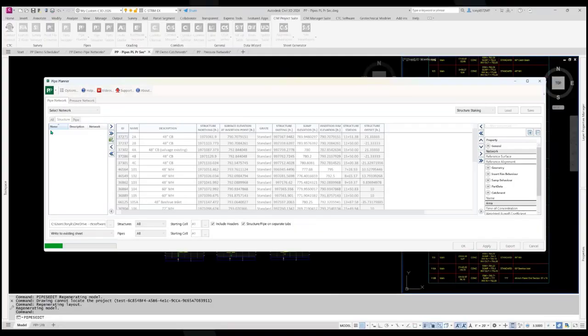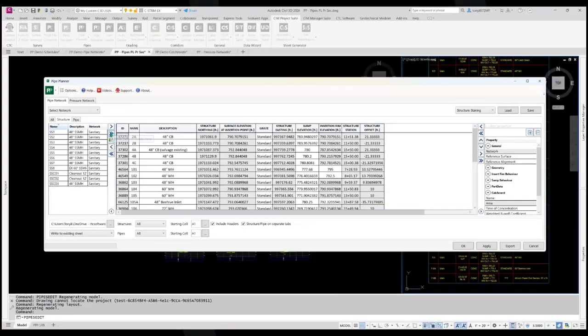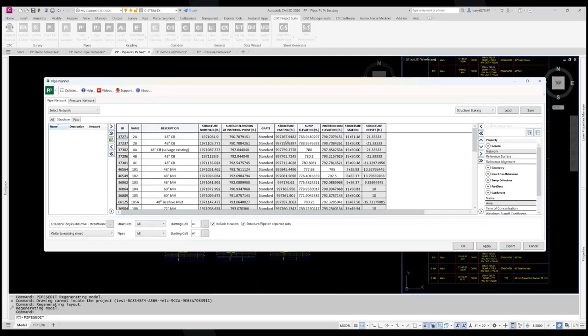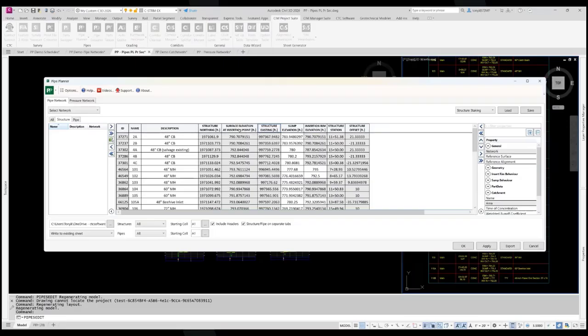That includes my sanitary. So I have everything I need right here. I have the name, description, northing, easting. There's my easting. I don't think I need that in there, so let's get that out of there. So I have my elevation, my northing, my easting. I'm going to push this one to the left. So rim, northing, easting, all the data I would need to stake that. So again, I can save this as a report.